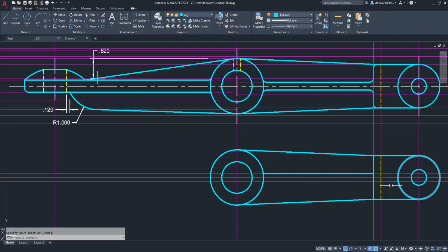And again, like I've been saying, I could just be doing this one time and mirroring the whole thing. I'm doing both sides actually for your benefit so that you can see me do the operations twice. Going to my fillet command now, clicking on the fillet button and typing R, enter. I'll enter in the radius of 0.12, and that's the radius we're going to use on everything.